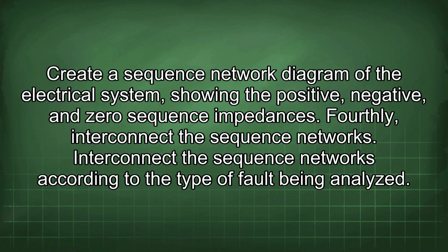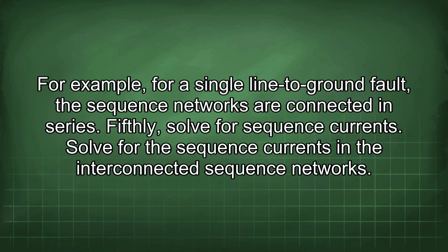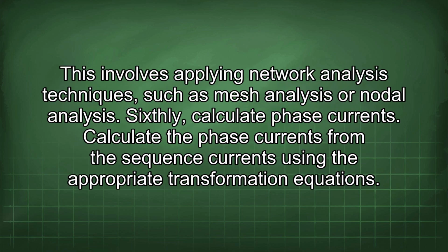Fourthly, interconnect the sequence networks. Interconnect the sequence networks according to the type of fault being analyzed. For example, for a single line to ground fault, the sequence networks are connected in series. Fifthly, solve for sequence currents. Solve for the sequence currents in the interconnected sequence networks. This involves applying network analysis techniques, such as mesh analysis or nodal analysis.